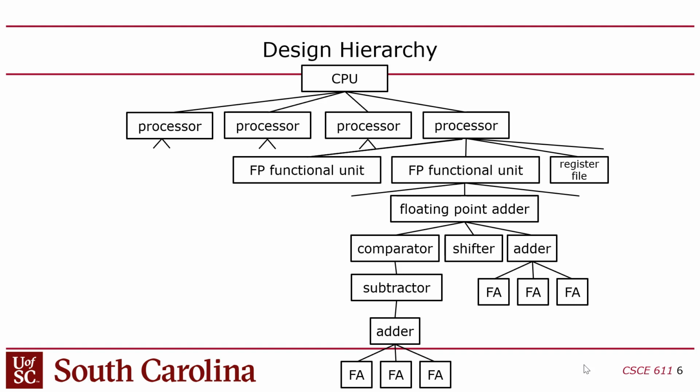So we're going to be using Verilog, or SystemVerilog actually. And Verilog is designed around the concept of a module, and modules are there in order to allow you to express hierarchy. So you can have a design that instantiates modules that also instantiate modules within them, and so on and so forth. So this is a way that you can describe a very complex design, but if you look at any one file, any one design, it looks rather simple, right?